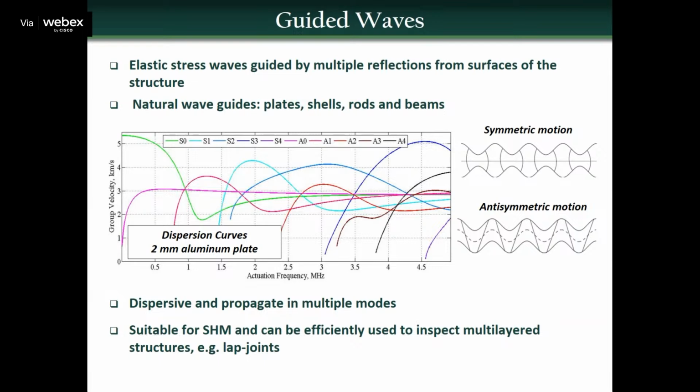They are elastic stress waves, as we've seen in today's morning session, guided by multiple reflections from the surfaces of the structure. The natural waveguides are plates, shells, rods, and beams, and they have complex dispersion curves, or the group velocity versus the actuating frequency.